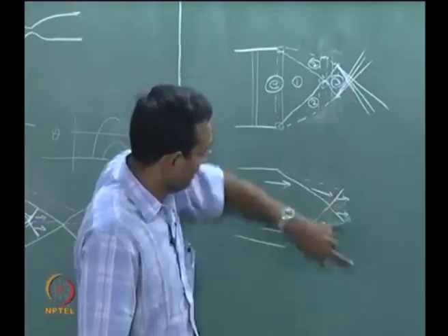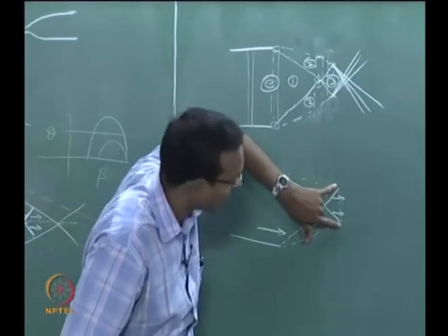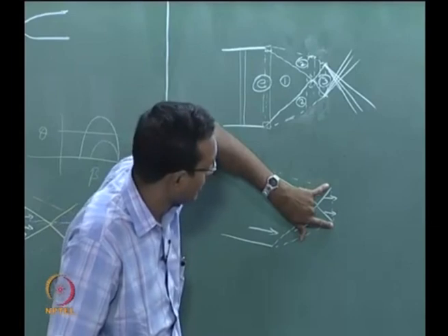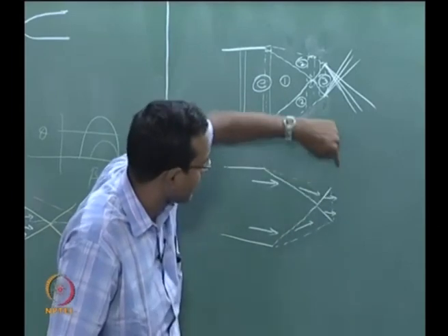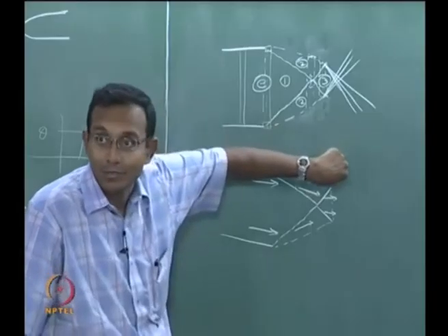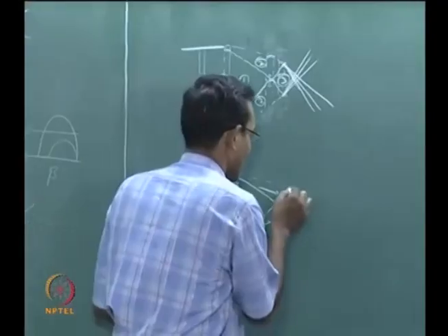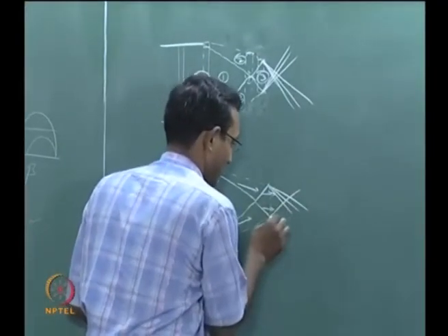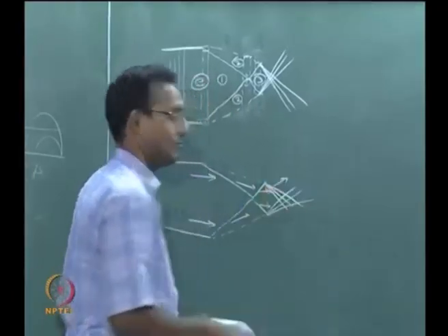The other way of looking at it is, it has got compressed and now I have a new jet going out like this, as if it is a shrunk jet coming out, and when that jet comes out, immediately it is seeing the pressure here is higher than the outside pressure. What should it do? It has to expand. So there will be expansion fans here, expansion fans here, and the fluid element goes out.